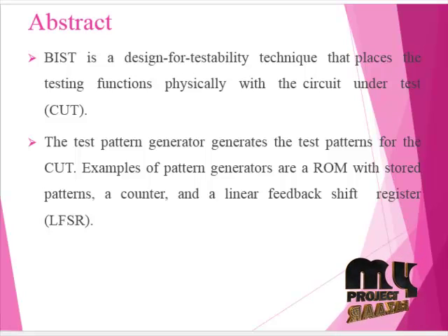It is comprised of a linear finite state machine, a linear feedback shift register or a ring generator as the finite state machine, driving an appropriate phase shifter, and it comes with a number of features allowing this device to produce binary sequences with pre-selected toggling activity. The method automatically selects several controls of the generator, offering easy and precise tuning. The same technique is subsequently employed to deterministically guide the generator toward test sequences with improved fault coverage to pattern count ratios.